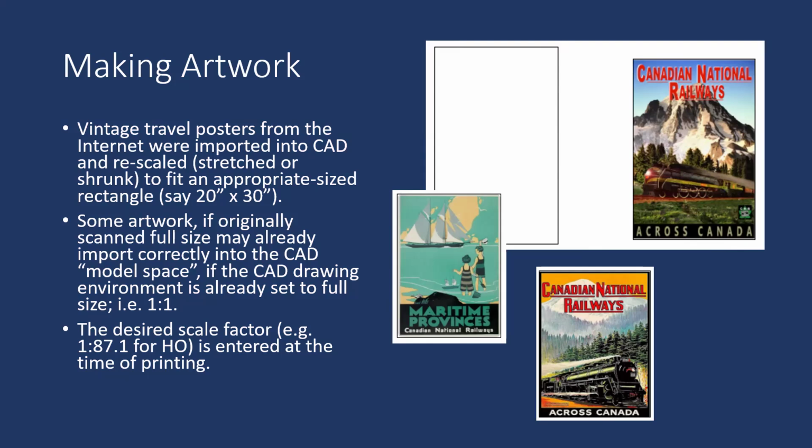Now, some artwork you may come across, if originally scanned full size, may already import correctly into the CAD model space if the CAD drawing environment is already set to full size, for example, 1:1. And then the desired scale factor, for example, 1:87 for HO, is entered at the time of printing.